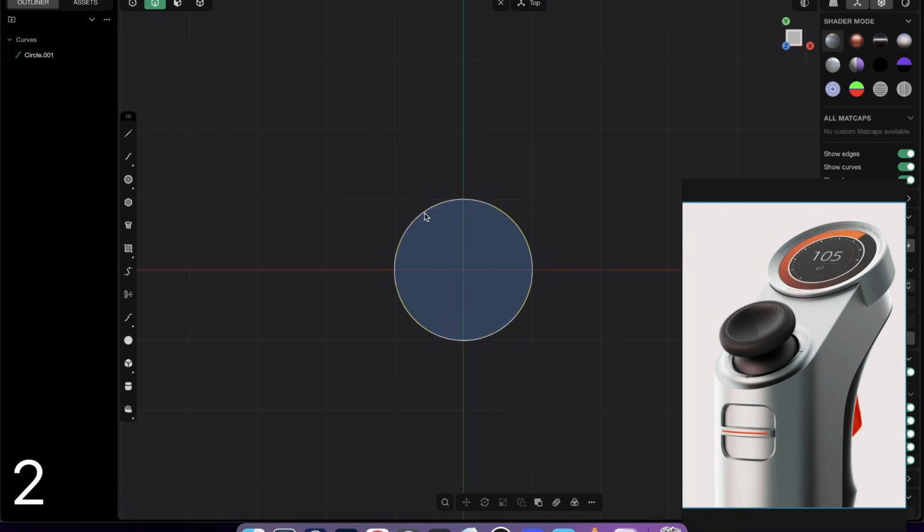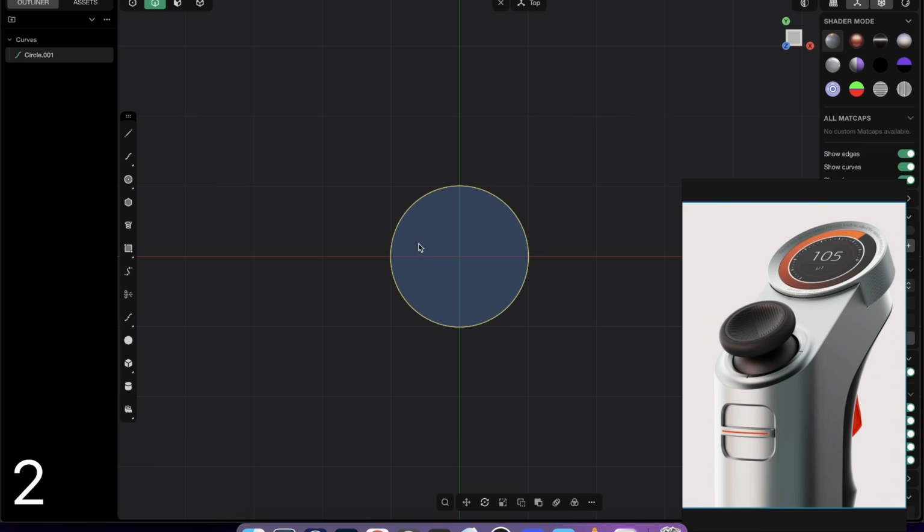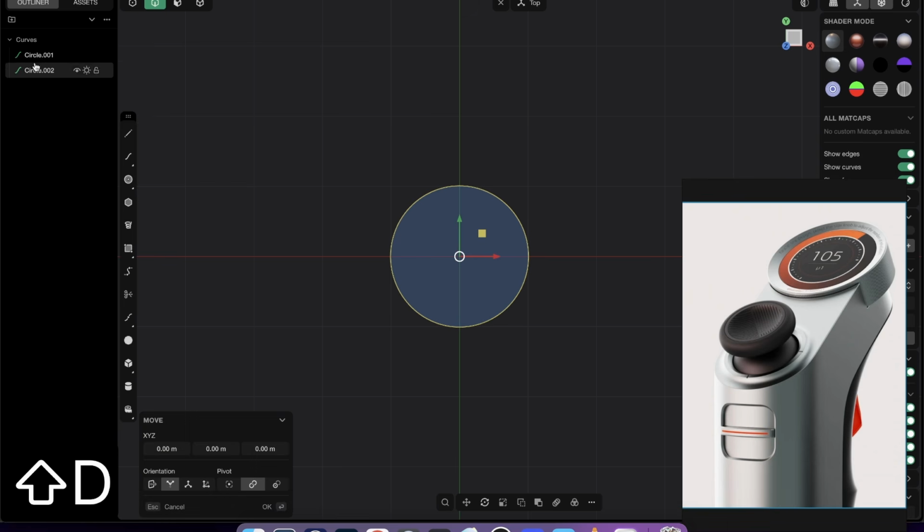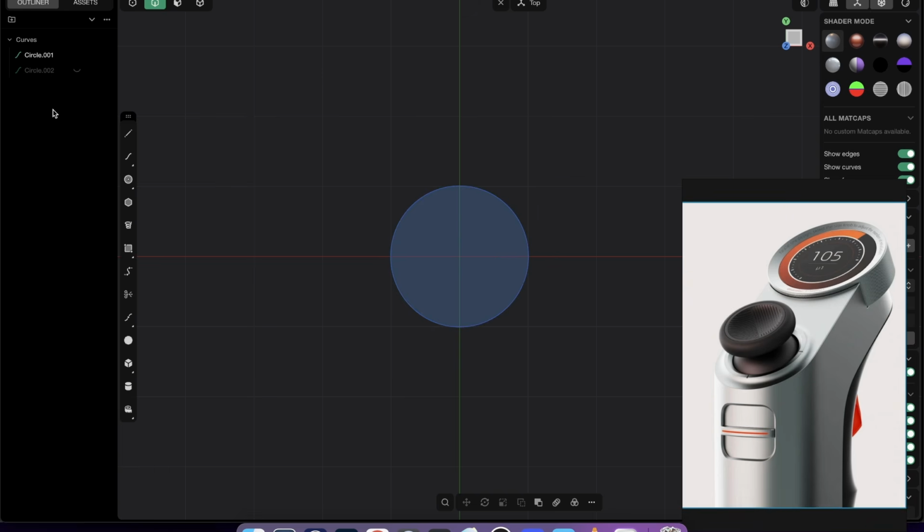And now, very important, select this circle and just press Shift D. That way you will duplicate it, because we will need it for the bottom piece, because we will need the exact same size, so everything will meet exactly. And just go here to the eye and click on it, because then one will be just hidden.